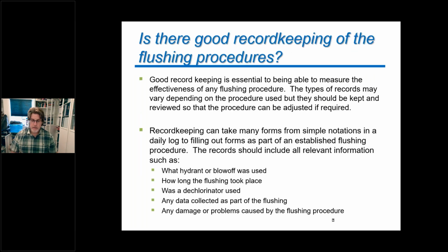And record keeping is important for everything. We need to really know, where did we flush from? How long did we flush? Did we use dechlorinator, right? Especially if you are in a sensitive area, you're near a fish-bearing stream or water body.